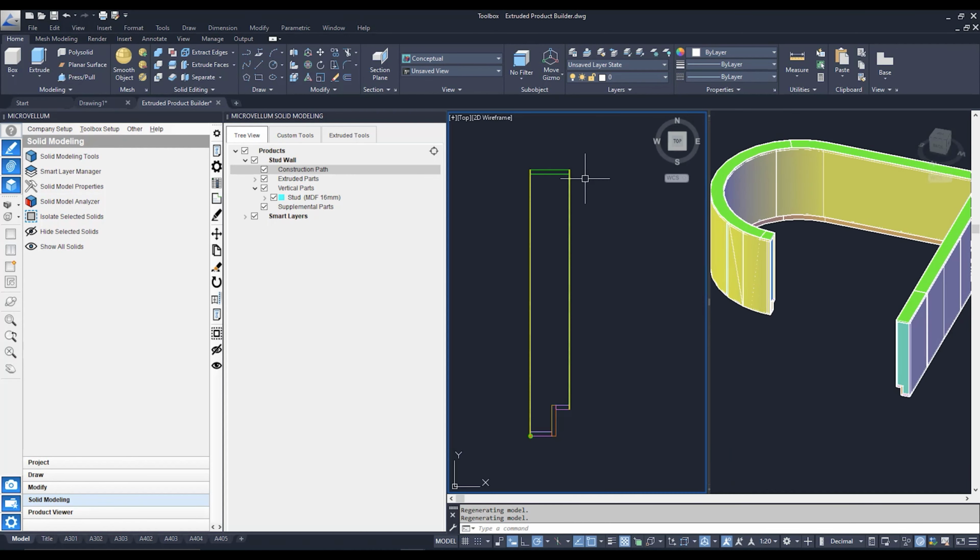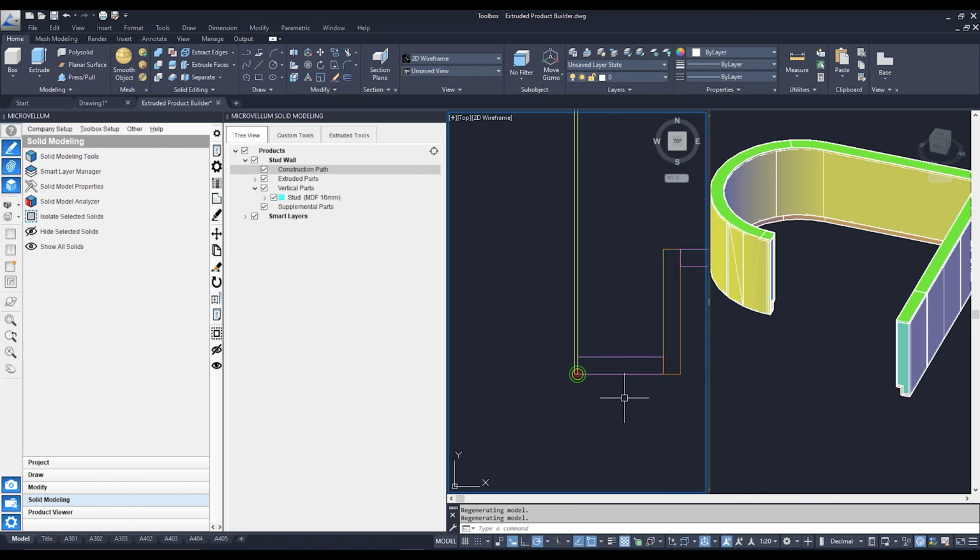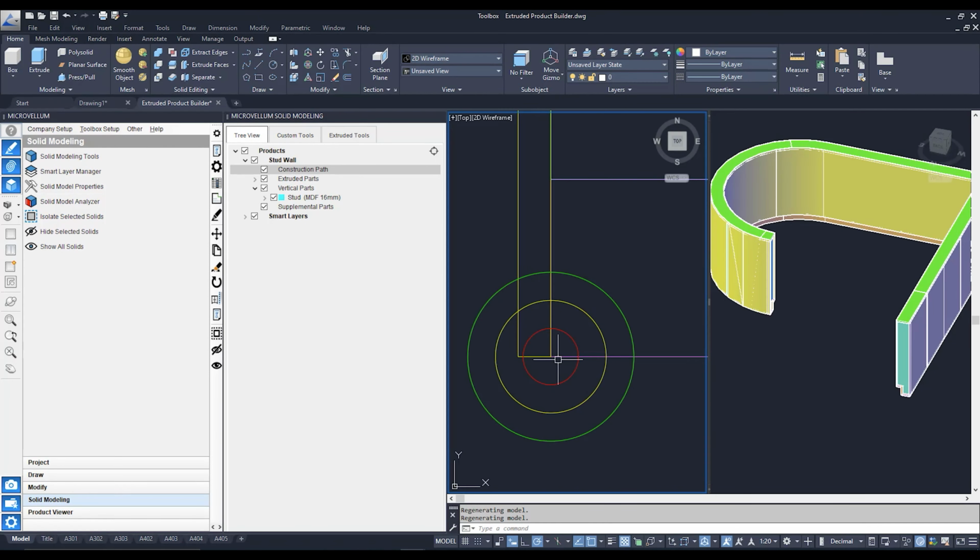Now we're going to circle back to our 2D guy because you probably noticed this happy little fellow up here. Now this guy here is pretty much saying that at this point, this 2D is extruded along that polyline. It's actually dropping in our extruded entity at this point, not here. So we need to move this guy over here. To do that, we're going to left click on our product within our solid modeling tools. We're going to right click and we're going to edit.